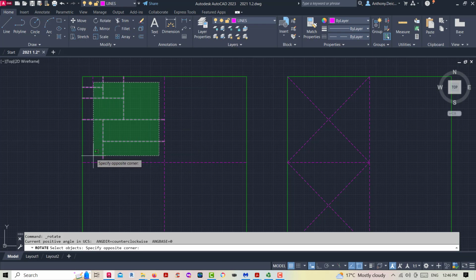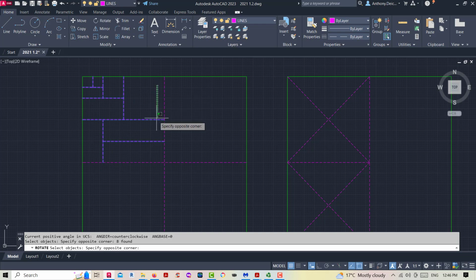I'll just select, I'm doing a right tap on my left mouse and moving it in the right direction. So one tap, let go of it, move it over from right to left, and then another tap. That allows me to select all those objects there by just having the rectangle pass through them. Once I've done that, you press enter.